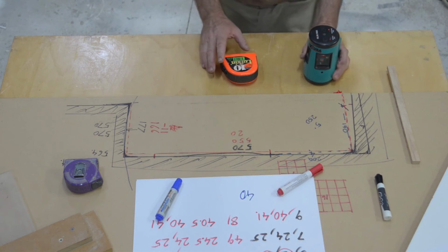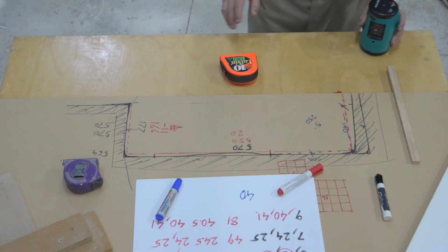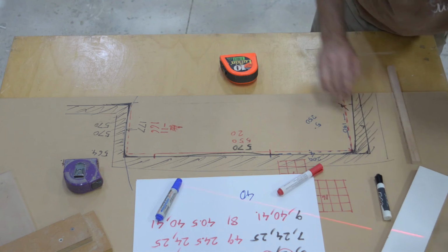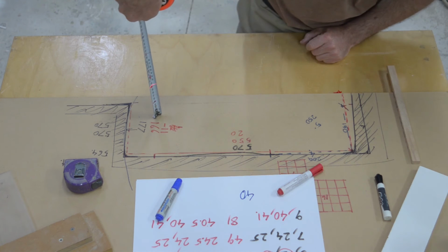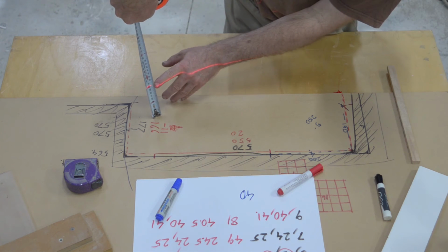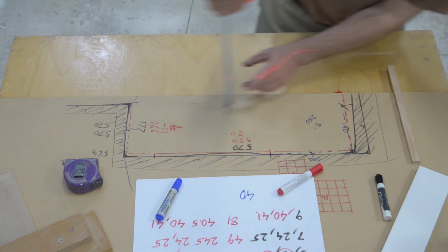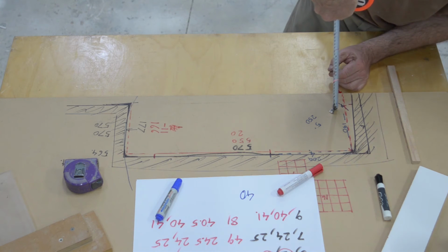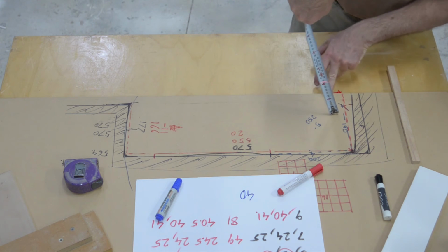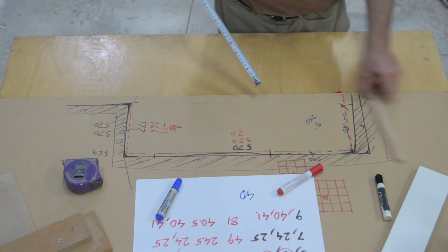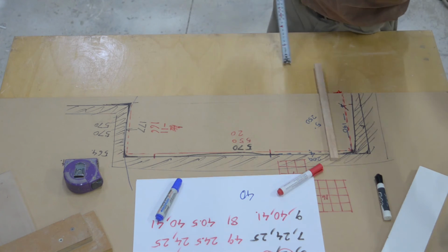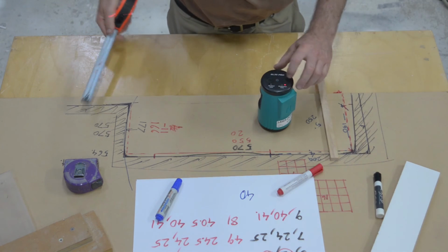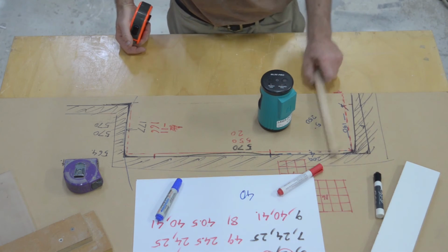Now I'll use that as an example by standing back here. I might put it on the other side. So I've just got, can you see that? Yes. That's showing 100mm or 101 there. And over here, the same. Of course, this little space on the workbench doesn't show up much. But if there was a variation in the floor of 10mm, it would show up with the laser. So a tool like this laser is very handy, but they are expensive.